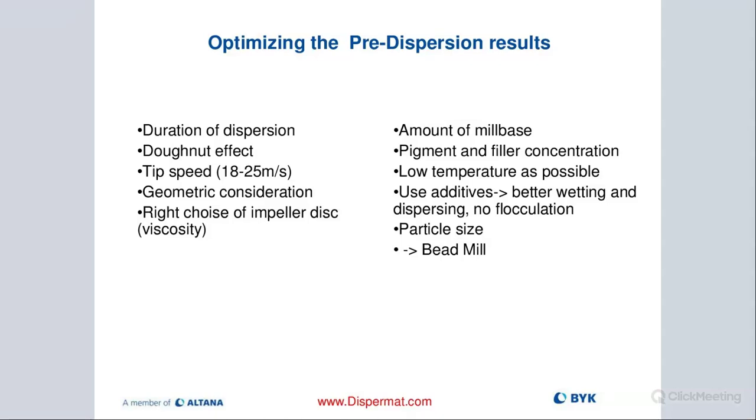It just basically means either your tip speed is not in the right range, or your viscosity is either too high or too low. When your viscosity is too low, like let's say water, then it's very difficult for a donut to appear, because it would automatically collapse as soon as it's trying to get formed, because there's not enough viscosity to really keep that donut going.